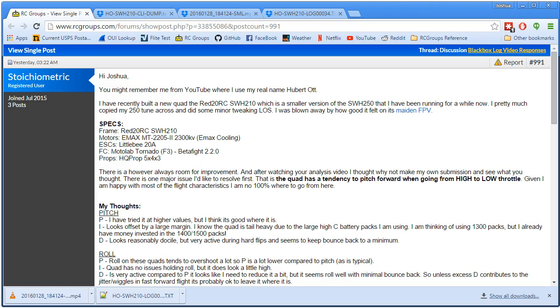And I moved it forward, so it was forward of center, and the I term changed a little bit, but not very much. So my conclusion was that there is a primarily aerodynamic effect that is causing this pitch back moment when in forward flight, and that is the primary thing that the I term is fighting, that the CG is having a relatively small effect here. You can test this for yourself.